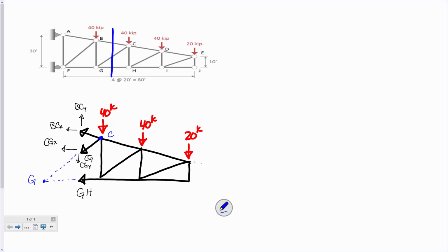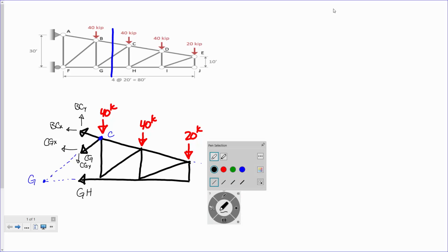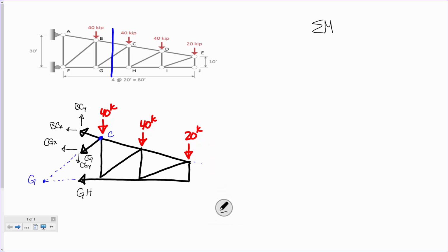All right. Now, for those of you that have had me for a structural engineering class or structural analysis class, which I don't think anybody in here, I sum moments a little differently. So this is what I like to do. I say sum of moments about point G equals 0, and then I draw myself a little table. And I say that all the moments spinning that way have to equal all the moments spinning that way. And then I just go through, like a bookkeeping operation, and start tabulating them down one at a time. So watch this.